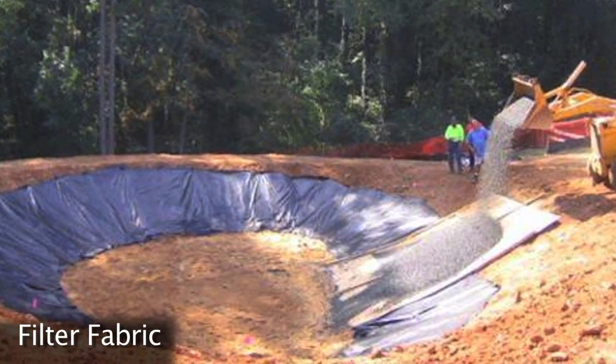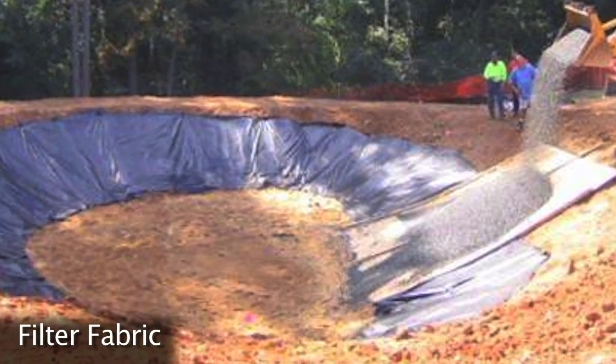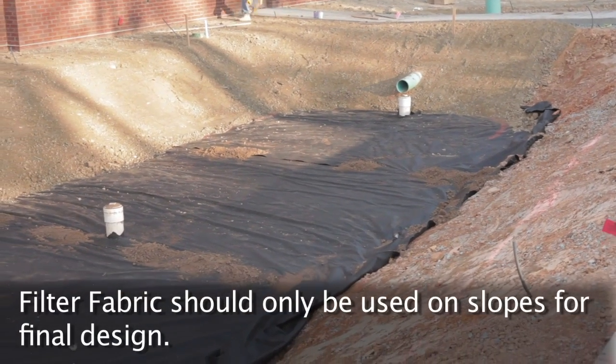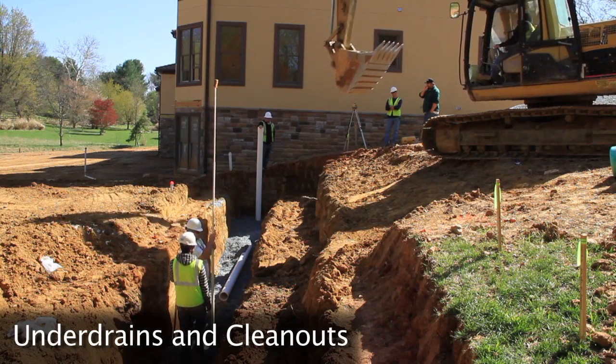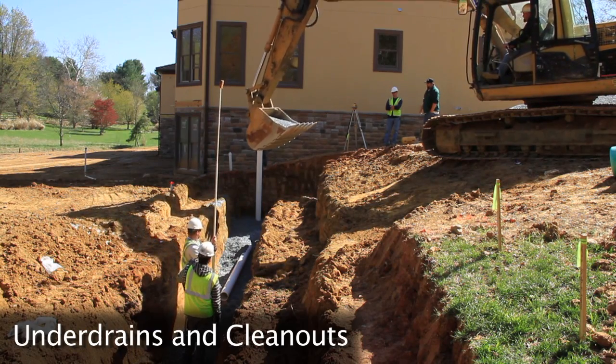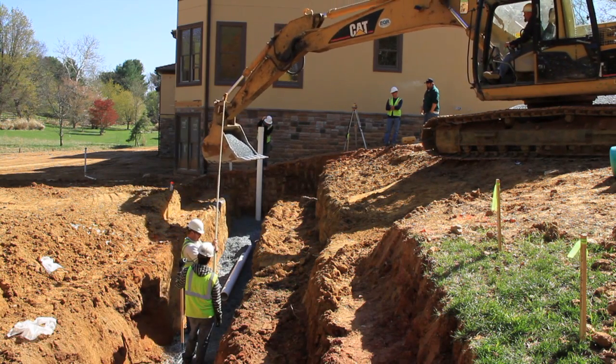We're starting to lose the parking lot and starting to lose the curb edge. Filter fabric can be used on side slopes, but should never be used on the bottom or in between the soil and stone layers unless an approved geotextile with a proper flow rate is specified by the design. Many practices utilize perforated underdrains to ensure the system drains at a desirable rate.